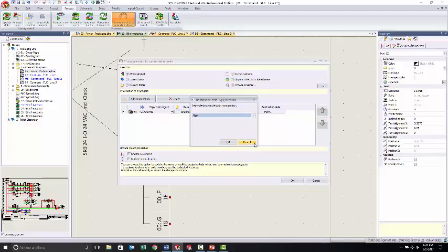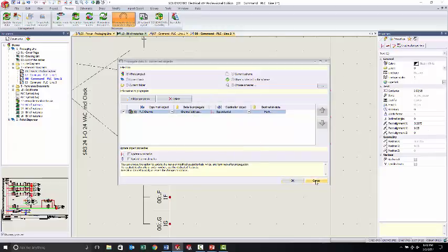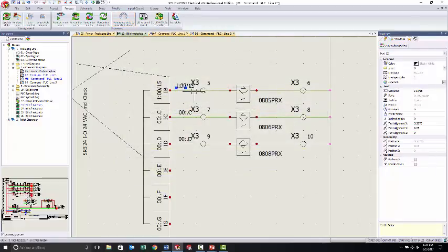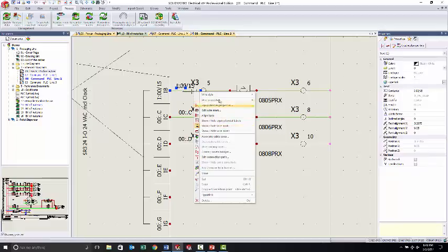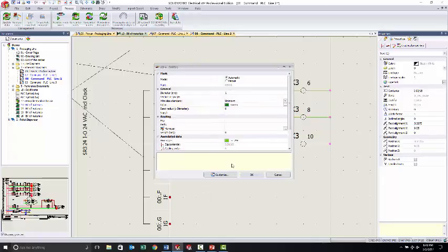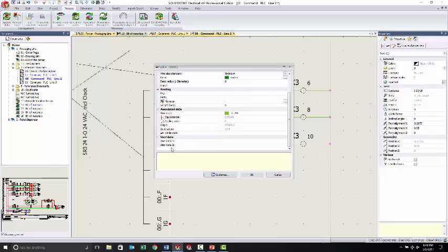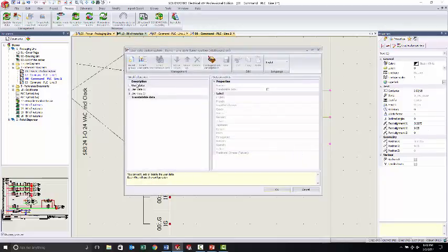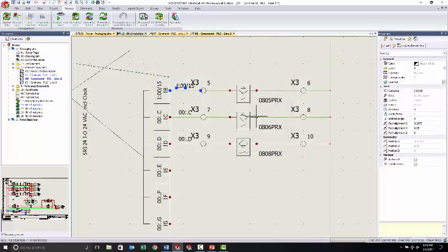So, if you were looking at this wire here, and if I right-click on that wire and go into the wire properties for that wire. Here under Customize, you've got user data down here, user data 1 and user data 2. You've got that possibility of creating up to 20 fields here that you could have pushed that number into instead. So that's what that is referring to here.